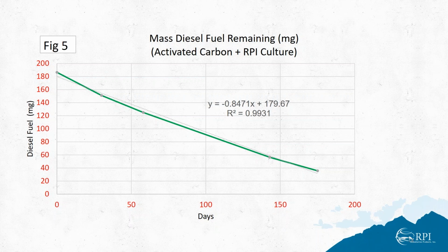The better way of looking at this is to look at it from a kinetics point of view. And that's what this is telling us, is that we now have a tool that we can use to actually start thinking about a timeline. So if we want to eliminate the NAPL that's there in 2 years, we can then turn that around and determine what the average loading needs to be in terms of the treatment on the BOS200 in order to achieve that.